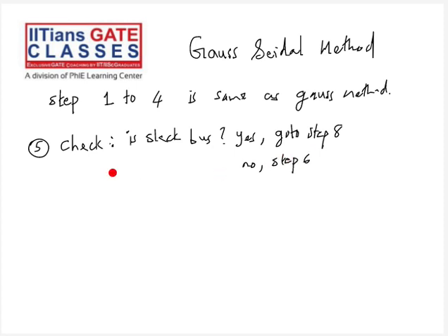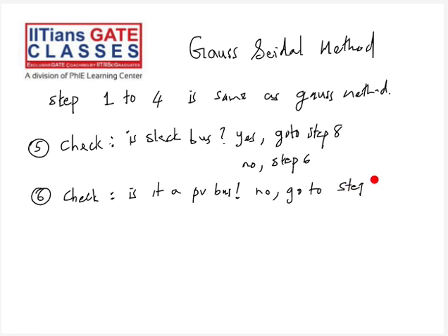If it is slack bus, we say go to end. If it's not slack bus, we proceed to step 6, right? So then we check, is it a generator, a PV bus or a generator bus, right? If it is no, you say go to the next step. Please skip whatever is being done here.